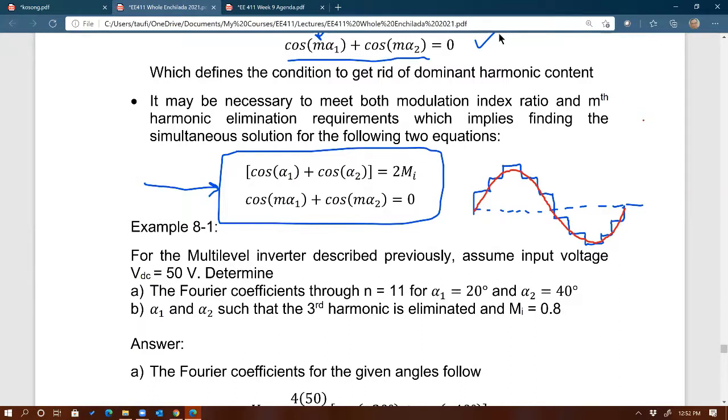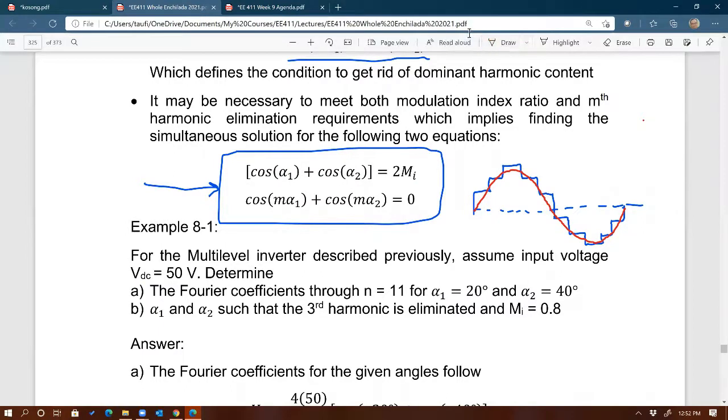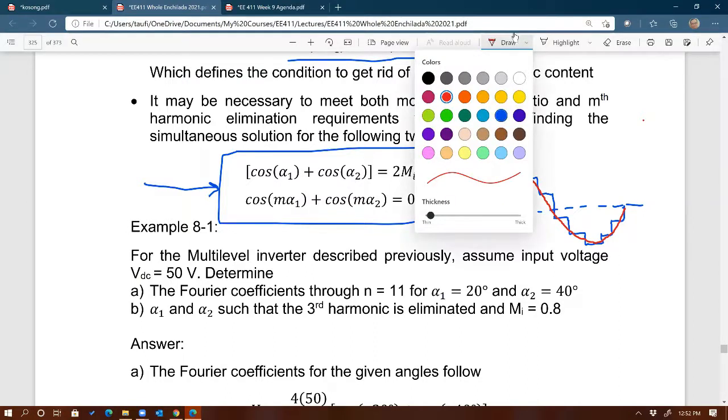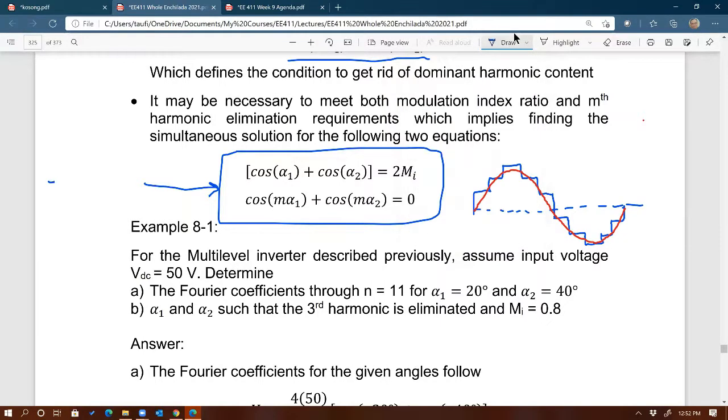Exactly, yes. So the blue, if you look at the Fourier components of the blue, it will be like this. So you have the first component, harmonic number 1, and you have harmonic number 3. This is the frequency domain, okay? And then you have the fifth, and the 7, and so on and so forth. You agree? That's the square wave.